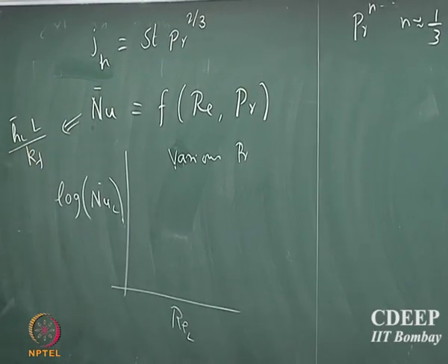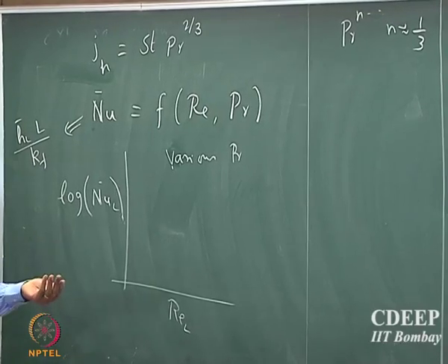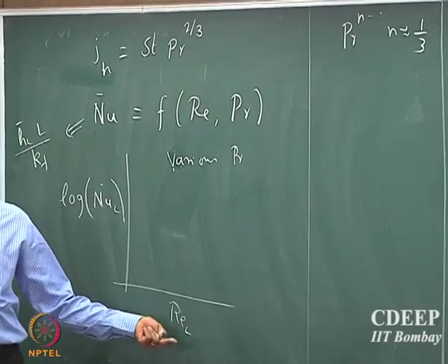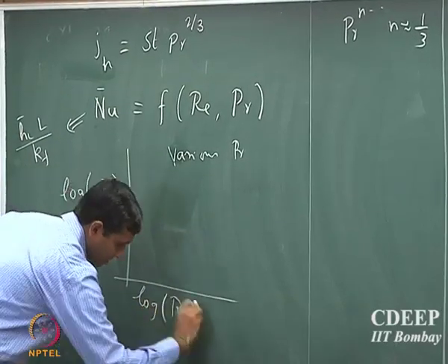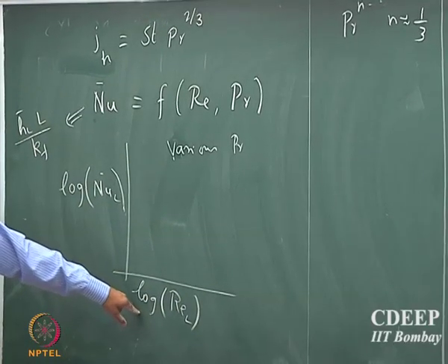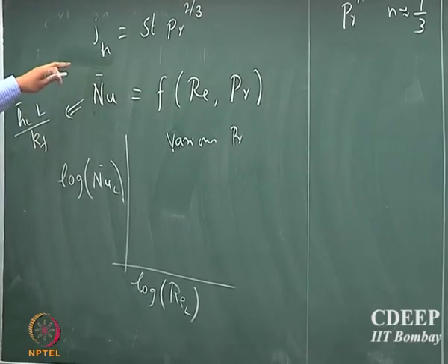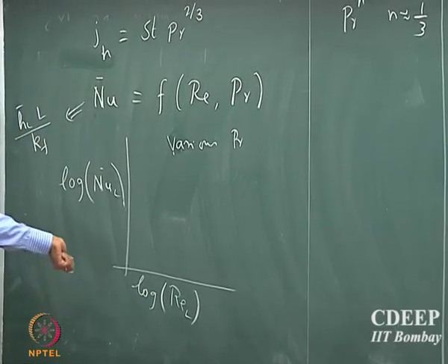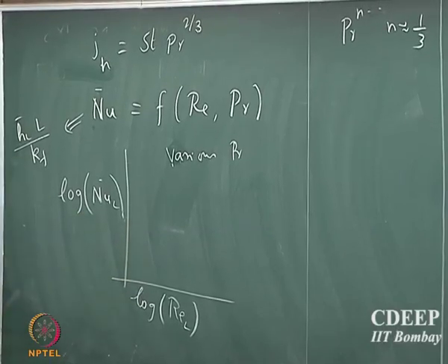So, you know Kf, you know the length, and you know the average heat transport coefficient from your experiments, and you know the Reynolds number of the flow. So, it is not by chance that they found you have to plot log, it is actually some of these theoretical Colburn analogy was used to understand what should be the functional form that you have to use to extract information from this data, okay.